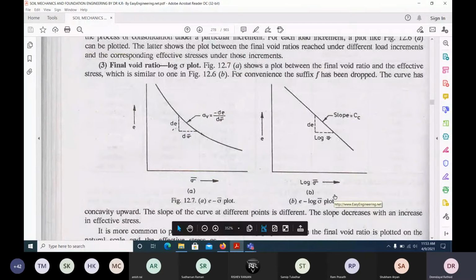Likewise, if you recall in the shear strength chapter, by using the triaxial test we used to find the Mohr circle, with sigma 1 and sigma 3. On the y axis will be shear, on the x axis normal. Then we plotted a number of Mohr circles and joined them with a tangent. Where it intercepts, what we found was the C, and the angle it gives is the angle of internal friction.